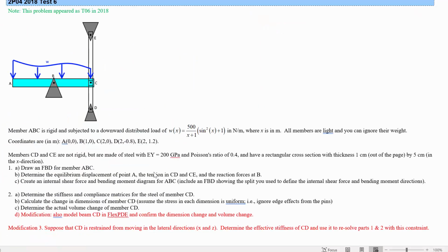So just to look back over this problem, what we did is started with this setup, drew a free body diagram for this beam, and then related the force in each of these beams to the displacement of this point and their elastic constants, their effective spring constants, which we determine from the stiffness of the beams and their cross-sectional area and their lengths and their material. I guess the stiffness as their material property. So using all of that, we were able to figure out what this displacement was and what this displacement was, what all the forces were.